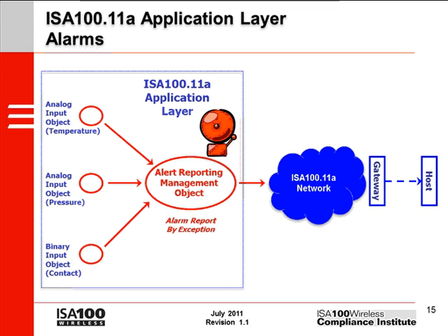When the value crosses the threshold in the opposite direction, the alarm clears and we see another message. For example, imagine an application that needs to report exceptions within 10 seconds. If we use only the publication approach, we need to transmit a message every 10 seconds, even when the data is almost exactly the same. Why should we waste battery and network resources just to tell the host that nothing interesting is happening? In many applications, alarms can make these extra reports completely unnecessary.